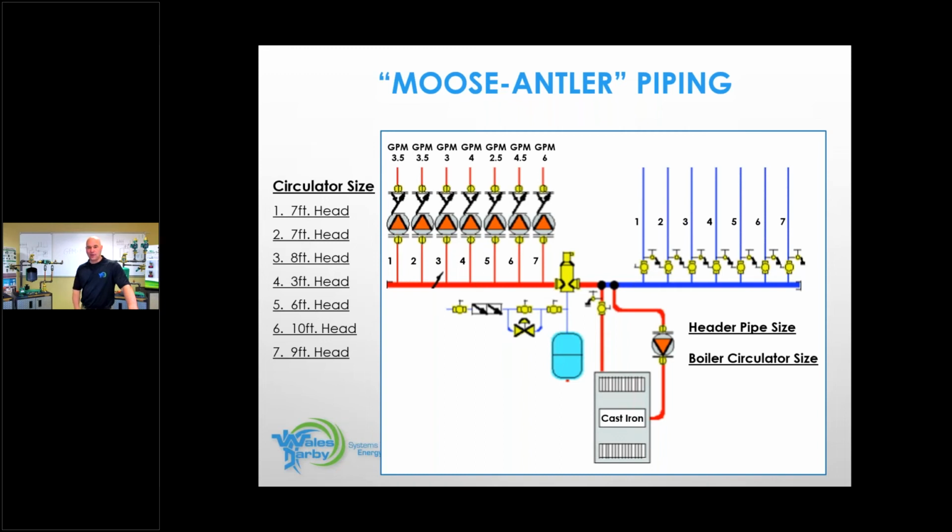Typically cast iron boilers in general will fall somewhere in the 2 to 3 feet of head loss. So you can go 2 feet of head loss on this job because of very short piping. Yeah, 2 feet of head loss will go with, at your flow rate, whatever it is. You have to figure out the flow rate. Two people have gotten the boiler flow rate, actually three.